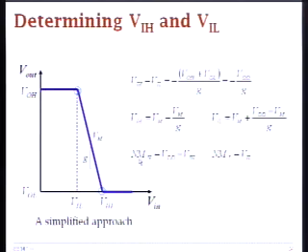And then you can calculate your noise margins. For high it is VDD minus VIH, for low it is VIL. So now what can we see from these expressions? Obviously it is very important to have as high a gain as possible, such that this transition region is very sharp, and therefore you have maximum noise margins. Because if you have a very high gain, in the limit case, when gain goes to infinity, your VIH and VIL will converge to VM.